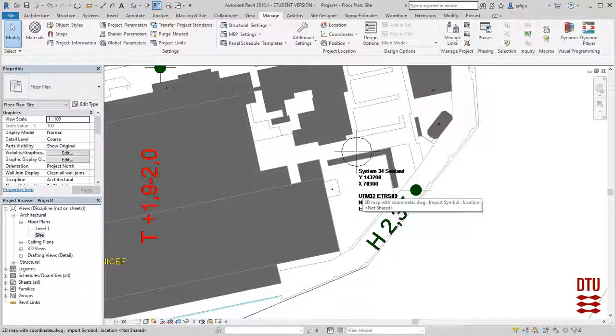At this moment, I have not positioned it in the level, but that will be the same. We will go into some kind of section or view, and then we can reposition or relocate the project so we will have it in the proper height. You need to put your building in a height where it is placed above this somewhere. But exactly where you will position your level 0 I am not sure at the moment, so for now I will let the vertical alignment be as it is.